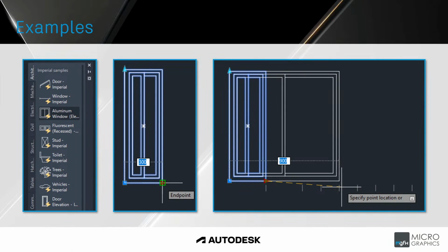Whereas you can actually just set up a dynamic block with those extents, those limits for lack of a better word, already populated in. You've got the same at the top there where you can extend its height as well. And so it goes on. There really are a very large number of dynamic blocks pre-populated into AutoCAD that you can make use of without the need to create your own. So be sure that you go through those before you create your own dynamic block. You could be putting a lot of time and effort into something that has already been done for you.